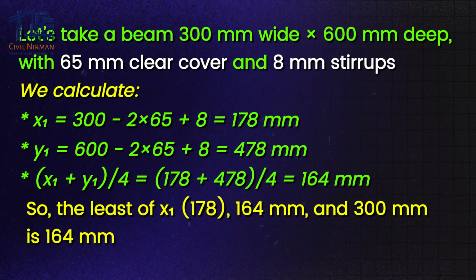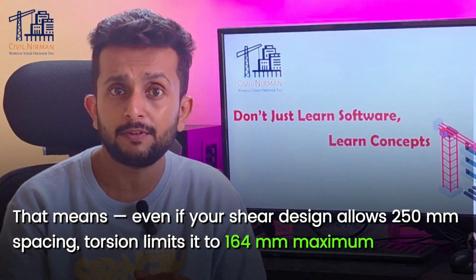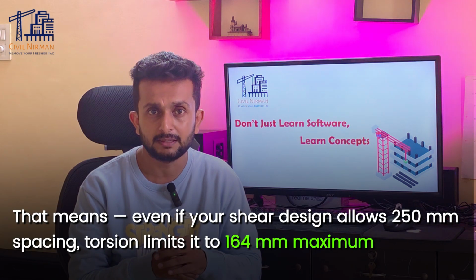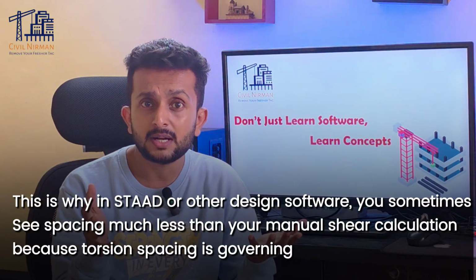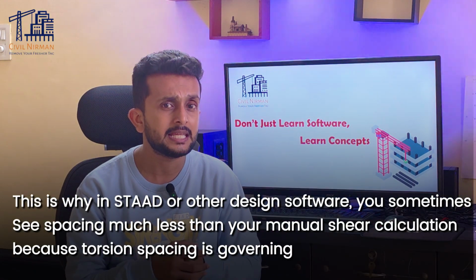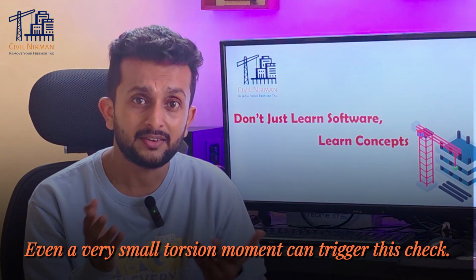So the least of all three, that is 178, 164 and 300 mm, the least is 164 mm. That means even if your shear design allows 250 mm spacing, torsion limits it to 164 mm maximum. And this is why in STAAD or other design software, you sometimes see spacing much less than your manual shear calculations, because torsion spacing is governing. So even a very small torsion moment can trigger this check.